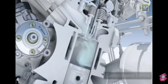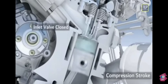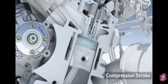Compression stroke. The piston starts moving up, the inlet valve is closed, and the air is compressed. The pressure and temperature of the air increase due to compression. Just before the piston reaches top dead center, diesel fuel is sprayed inside the cylinder.